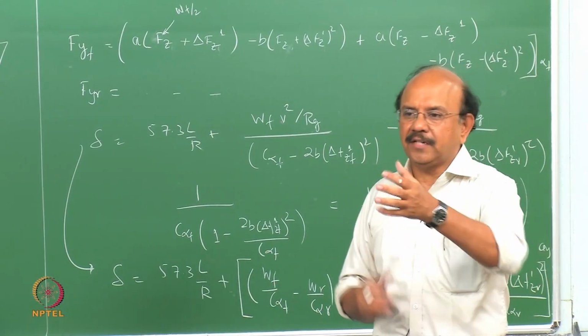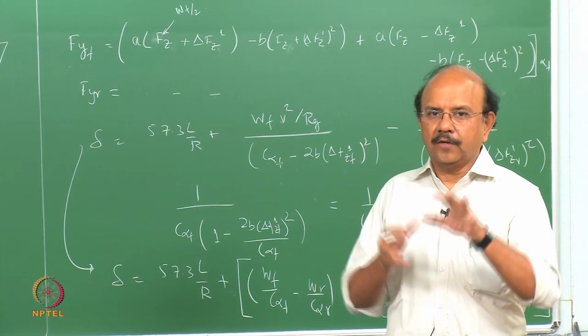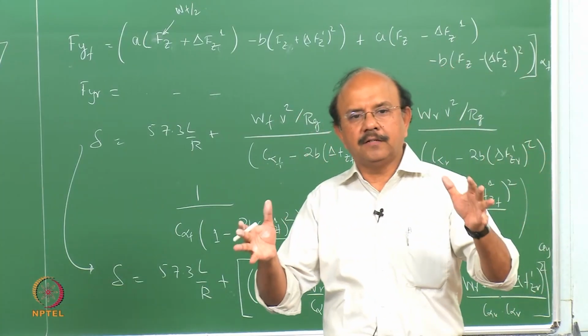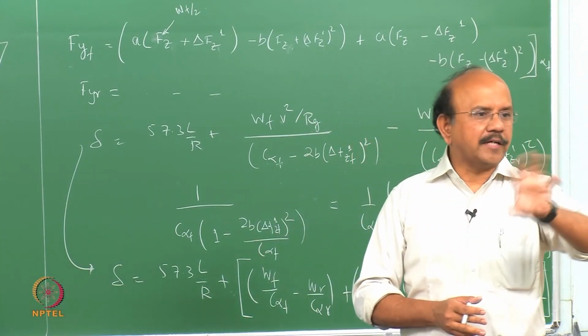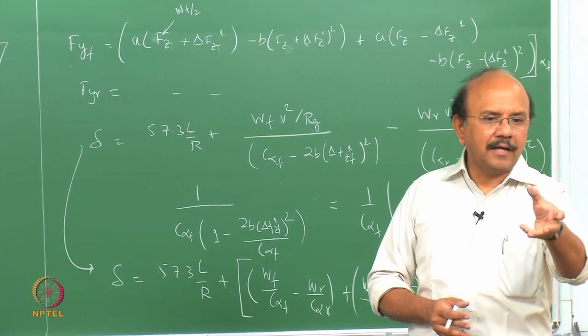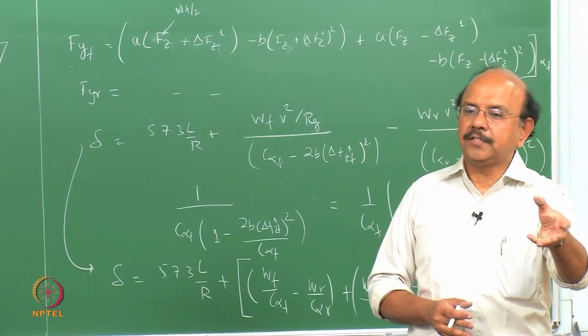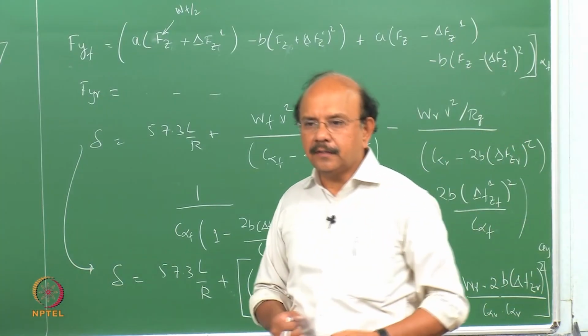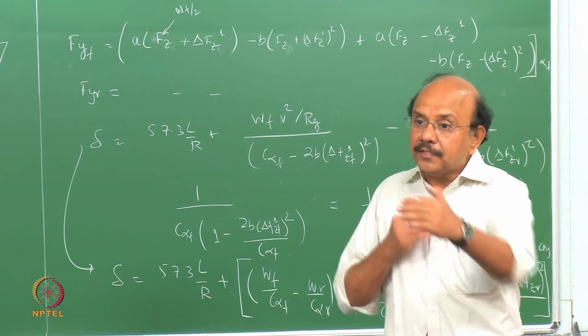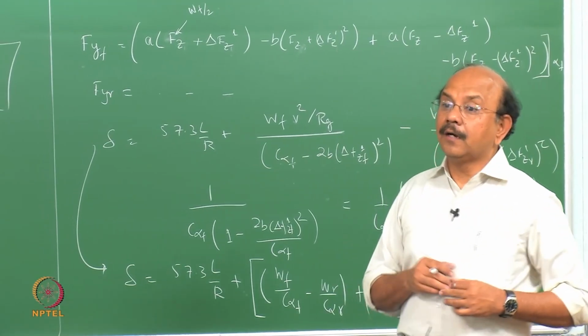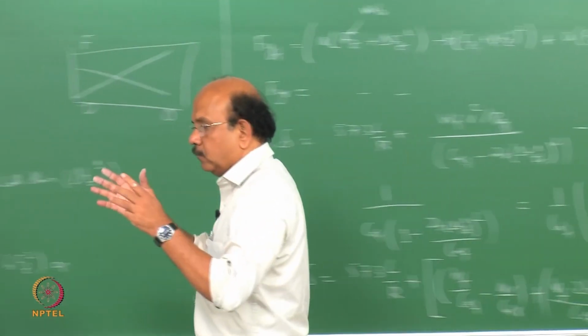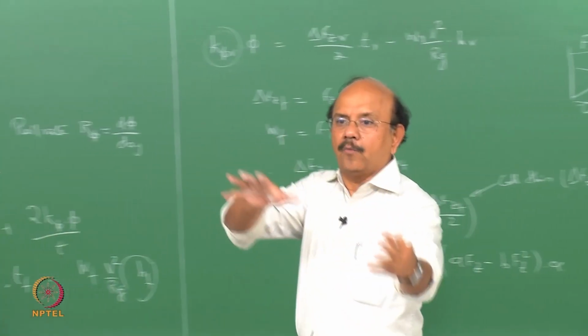So there is a transient region, okay, when the body was straight, and as you take a turn, the body actually rolls. So then afterwards it may settle down into a steady state when you are taking a steady state cornering. So there is a transient region under which the roll, which was 0, will take on a value.